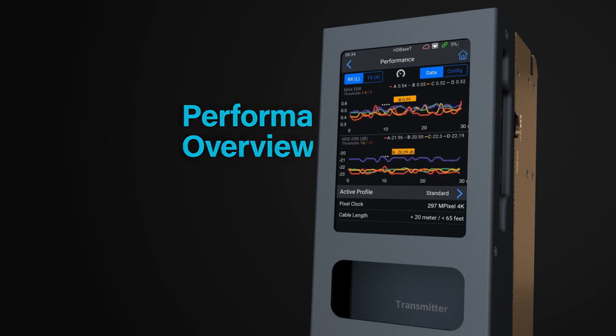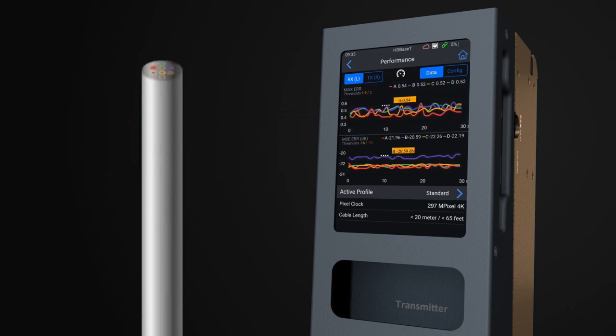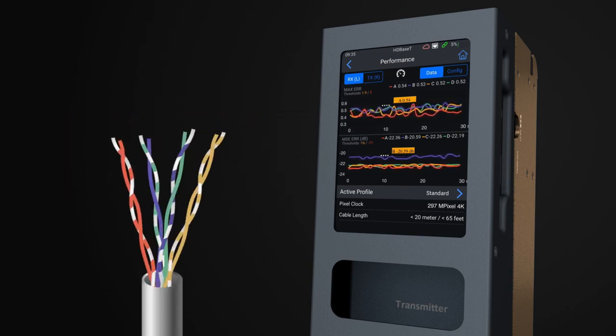The top graph is the max error rate, which signifies the maximum error rate the HDBaseT chipset is correcting errors to, that are picked up along the length of the cable run. The coloured lines are related directly to the twisted pairs in the cable. Pair A is for orange and white and orange, B for green and white and blue, pair C is for blue and white and green, leaving pair D for brown and white and brown.